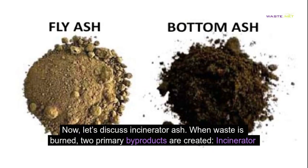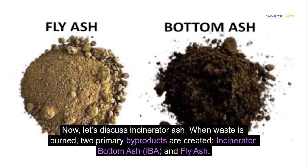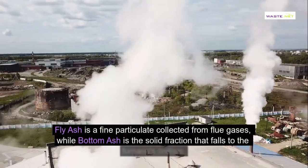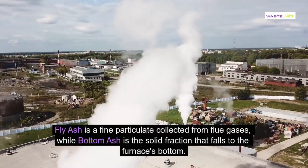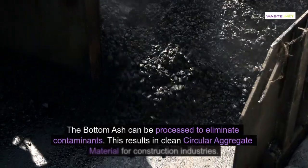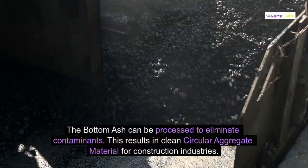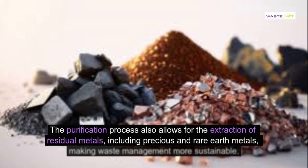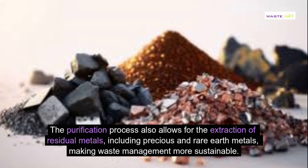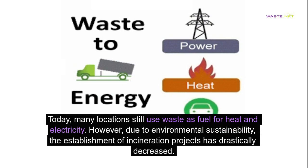Now, let's discuss incinerator ash. When waste is burned, two primary byproducts are created: incinerator bottom ash, IBA, and fly ash. Fly ash is a fine particulate collected from flue gases, while bottom ash is the solid fraction that falls to the furnace's bottom. The bottom ash can be processed to eliminate contaminants. This results in clean circular aggregate material for construction industries. The purification process also allows for the extraction of residual metals, including precious and rare earth metals, making waste management more sustainable. Today, many locations still use waste as fuel for heat and electricity.